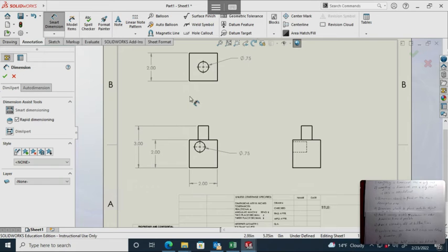So I have defined the size of this circle. I also need to define the location of this circle. So I'm going to draw a dimension out here. And we talked about how it's going to put the dimension lines on the outside. Now, if I can sneak the dimension inside, fine. If not, I can put it outside as well if it's a smaller gap. But that's a big enough gap, so we'll put that dimension inside.